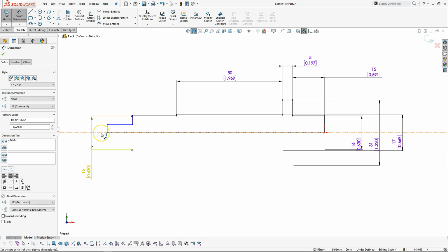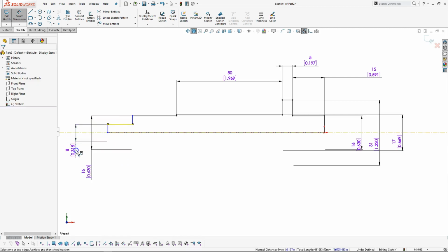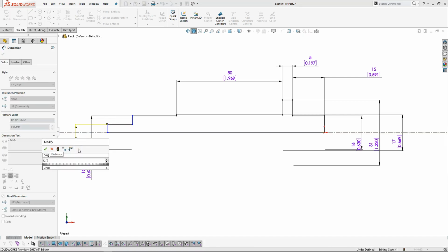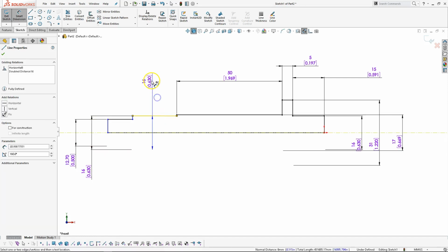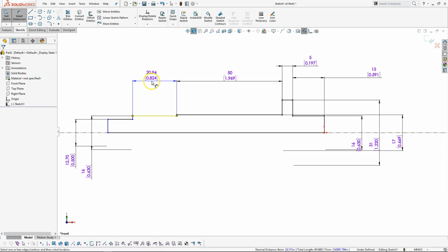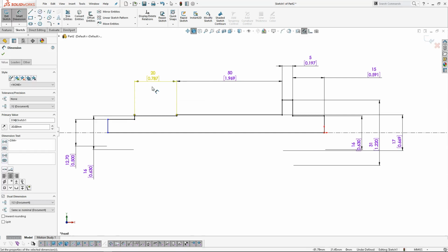And then the shaft, let's start with 1/2 inch, so 12.7. Alright, and then lengthwise, I'd have to look at a jam nut or pick out a piece of hardware on that one. So let's start with 20 millimeters, and we'll see how far that goes.